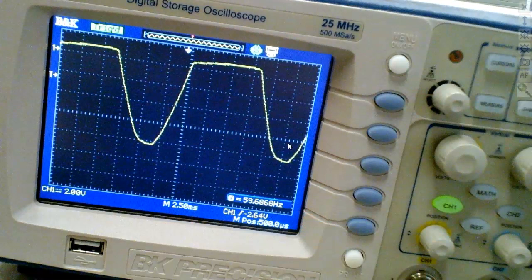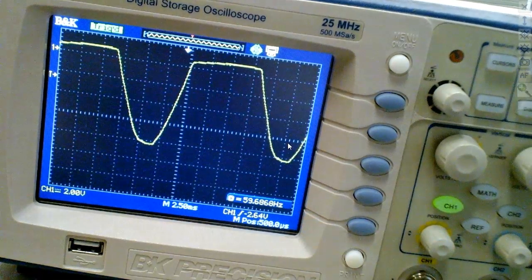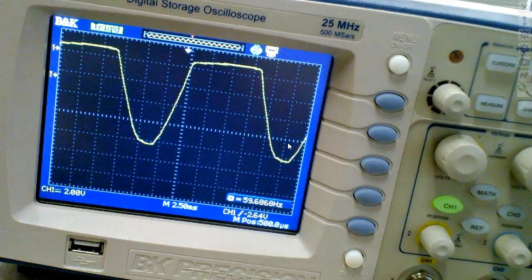Then I would multiply it by 2.5 milliseconds, and it should give you around 16. It's going to give you 16, but we know it's actually 16.6666 milliseconds. So making measurements on your scope is not extremely accurate because of the resolution of the scope, right? You understand that?